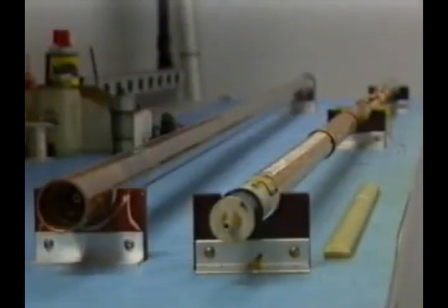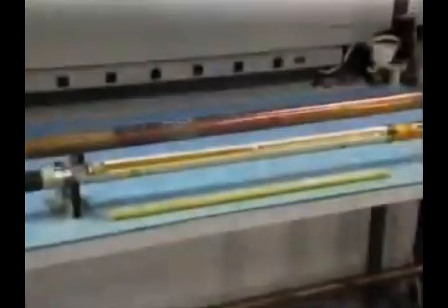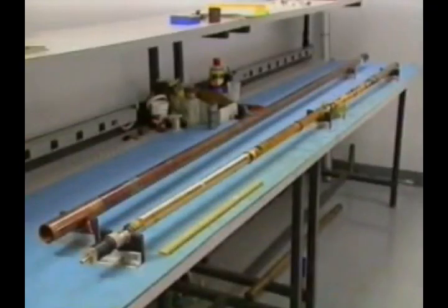The basic components of the MWD instrument package shown here include a battery-powered pulsar module, which in this case employs a continuous mud wave transmission, a sensor module containing triaxial inclinometers to measure drift and triaxial magnetometers to measure azimuth, along with temperature and pressure sensors, and an electronics module. This particular tool, together with its accessory modules containing the batteries and centralizer, is run inside standard non-magnetic drill collars.